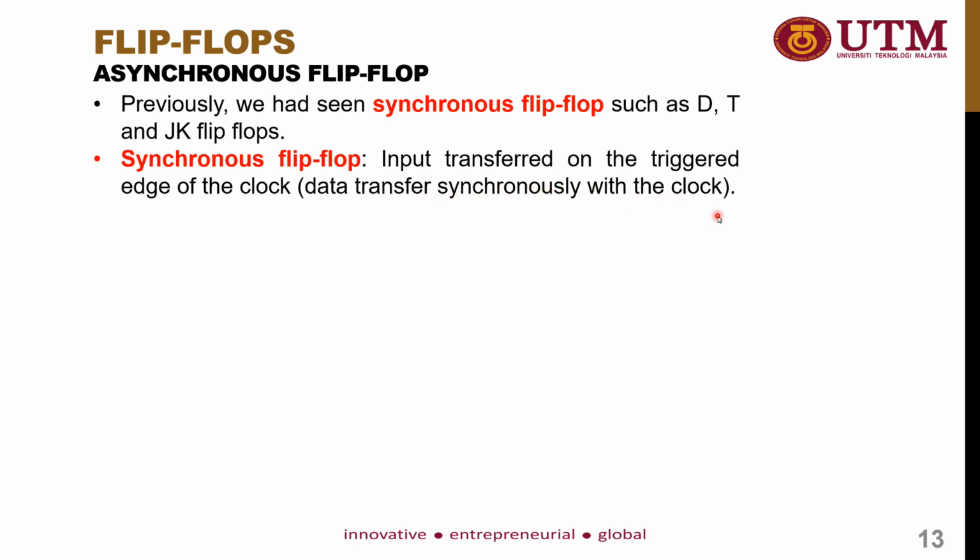From this definition, we can conclude that a synchronous flip-flop is a flip-flop where the input is being transferred synchronously with the clock. It means that the input can only be transferred during the positive edge or negative edge of the clock. So the input transferring will solely depend on the edge triggered inside the clock.